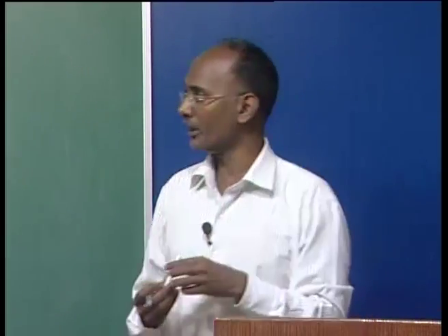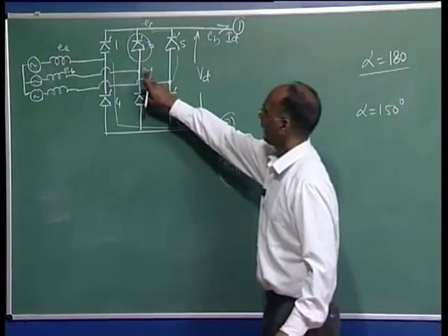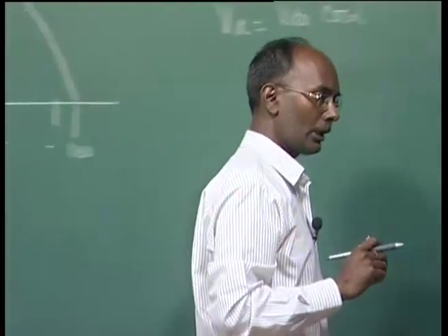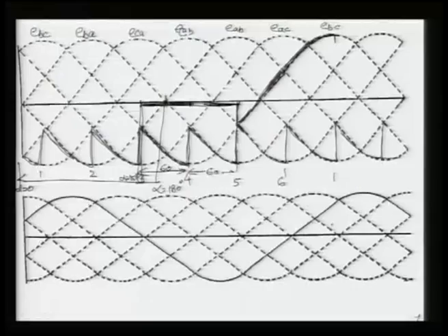So, the voltage across valve 3 is EBA, because B is here and A is coming here. This is EB minus EA voltage, always we are drawing the direction. So, EBA, and now you have to see where the EBA is. You can see EBA is this one, and it will follow here and then it will continue. Here 1 is fired, then even though 2 is fired, it won't affect its voltage, because it will continue till 3 is fired.